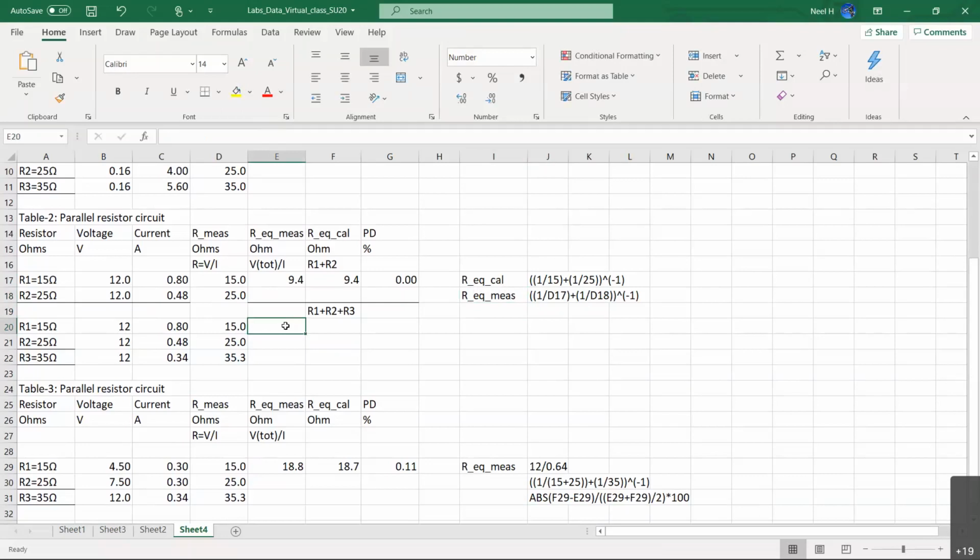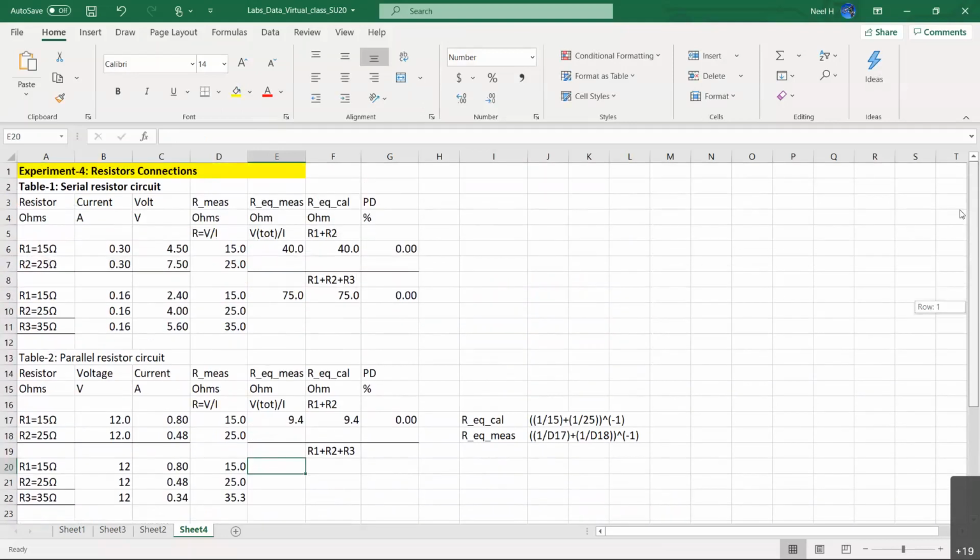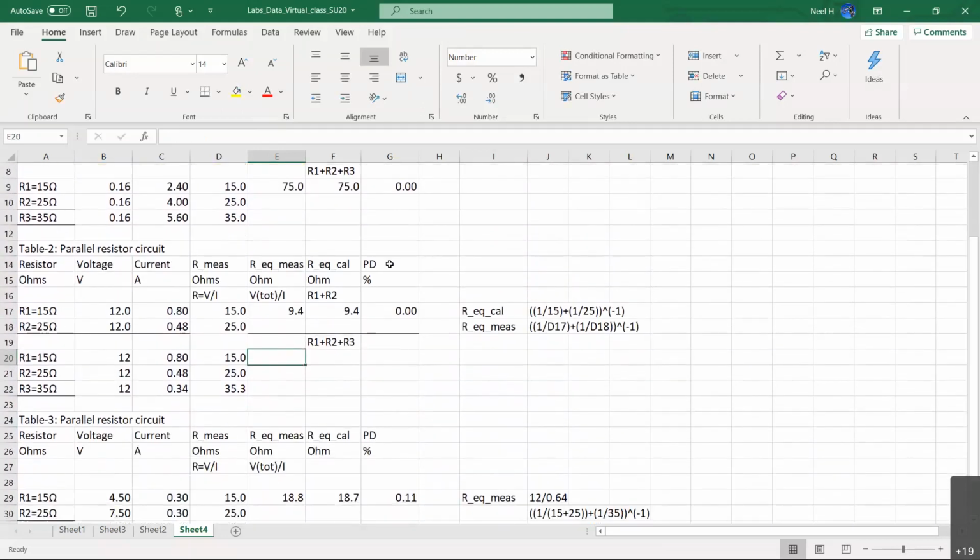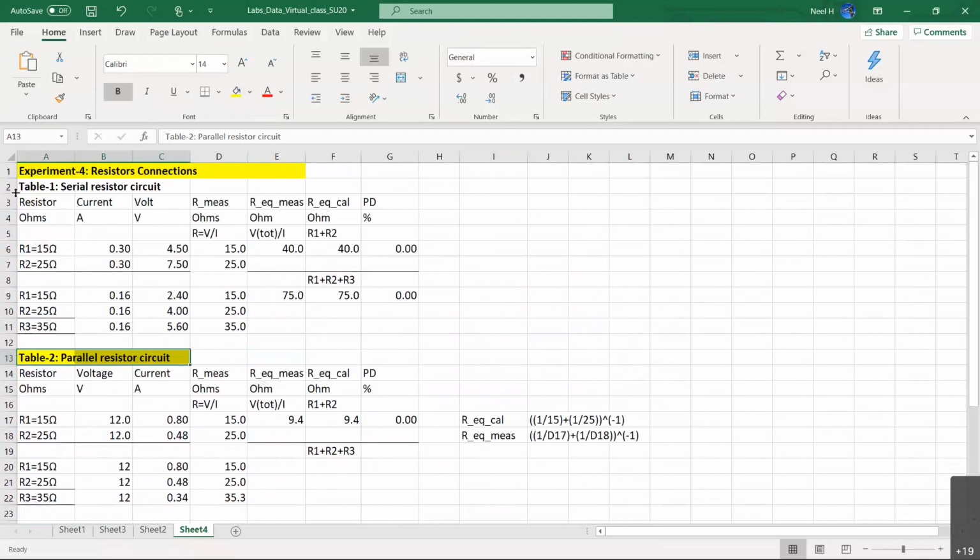Any question? Yeah, that's a good point. There's a table number 2. Small error earlier. Make sure table number 2 is a parallel circuit, and then you do all the calculation inverse addition. Okay, otherwise you will get a completely wrong answer.